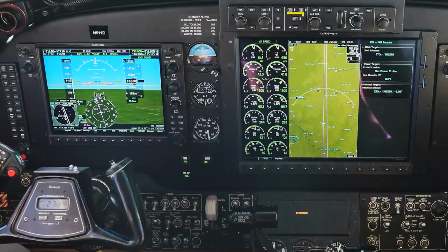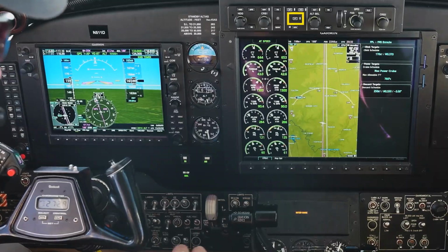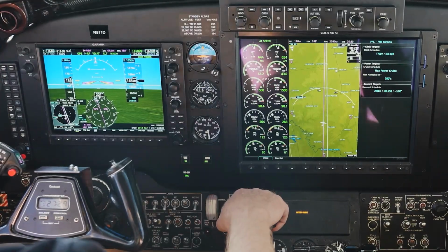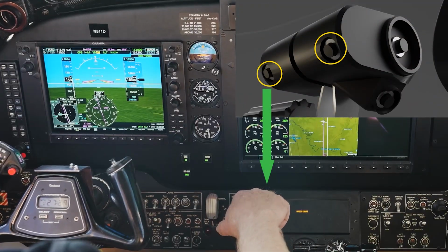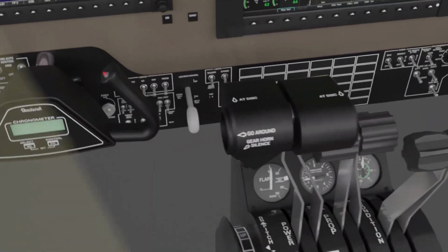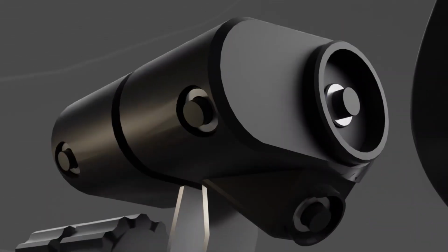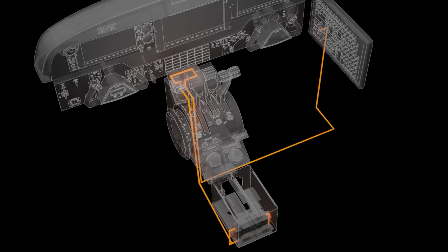While you can disconnect the autothrottle using the AT key on the mode controller, the primary means to disconnect the autothrottle is by using the AT disconnect switches on the power levers. The switches are ergonomically placed, so your fingers naturally rest on the switches when your hands are on the power levers. Power to the solenoid that engages the servo clutch travels through the AT disconnect switch. Pressing either switch will momentarily remove power from both servo solenoids and disengage the clutch, disconnecting the autothrottle.